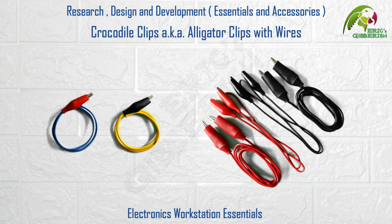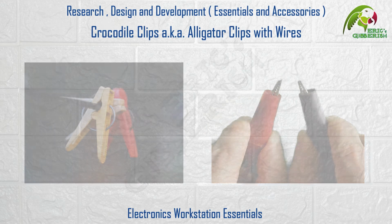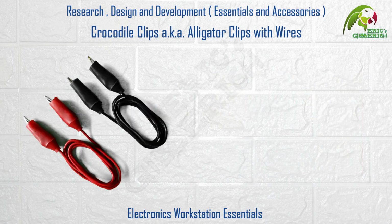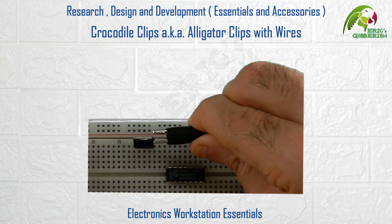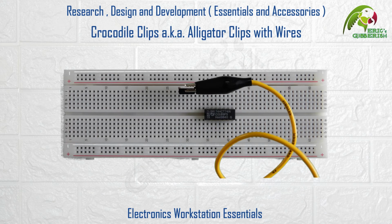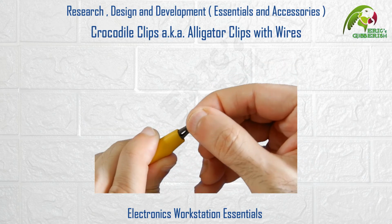Crocodile clips, also known as alligator clips with wires. Its design is very similar to that of a spring-loaded clothespin, and its name is such due to the resemblance of its jaws to that of a crocodile or an alligator. Available in various sizes like these standard size clips or the miniature ones that are comparatively smaller in size. These clips prove very useful at making temporary electrical connections between components, devices, modules, etc., and come with such colored plastic boots to prevent an accidental short circuit.